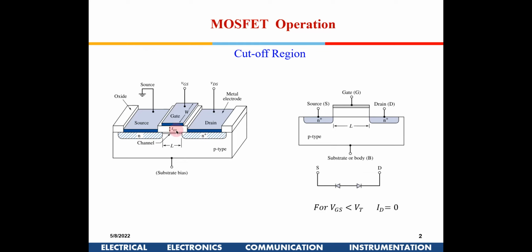HfO2 has almost 4 times the K of silicon dioxide. So instead of using, just as an example, a 1 nanometer silicon dioxide, I can use a 4 nanometer HfO2. Both will have the same electrical characteristics, but using 4 nanometer will prevent leakage currents from the gate side. Okay, so that is the gate oxide out here, and over that we have a gate.